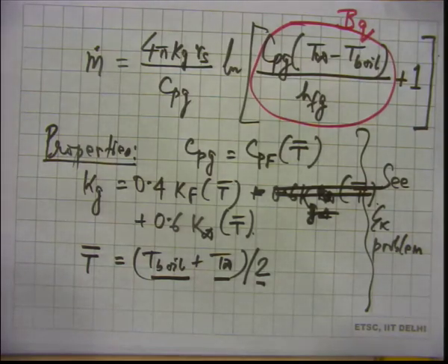When we go to droplet combustion, we are going to see something very similar, and we are going to get another B number. This is the B number for the evaporation situation. Okay. So, we can get m dot, but it will be a little bit more interesting if we also find out some expression for droplet lifetime.